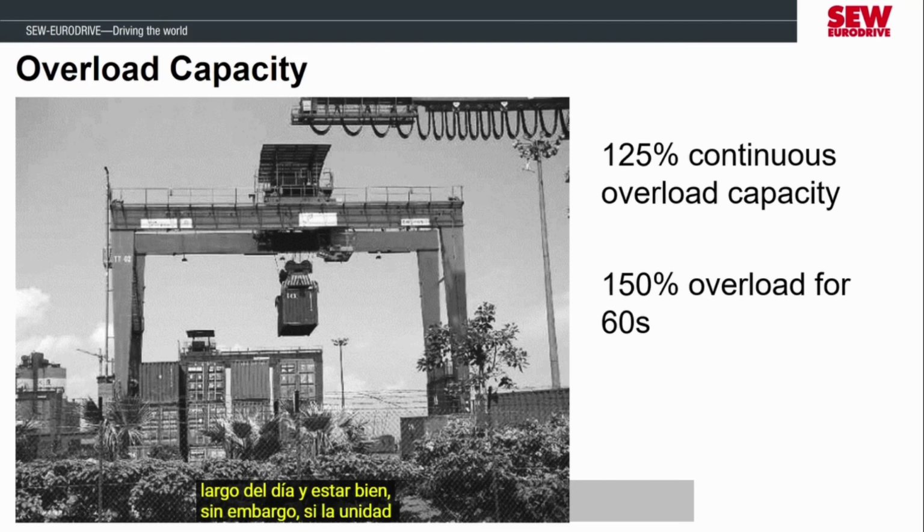However, if the Movidrive is continuously reaching 150% and holding it steady, then there is likely a mechanical issue occurring that will need to be resolved.